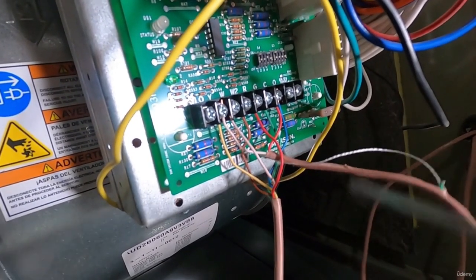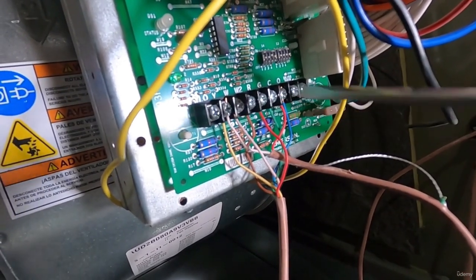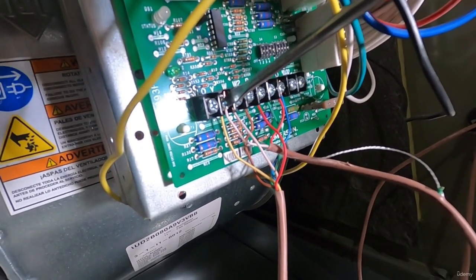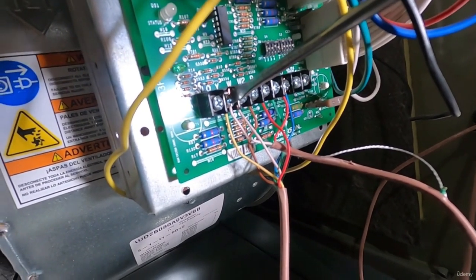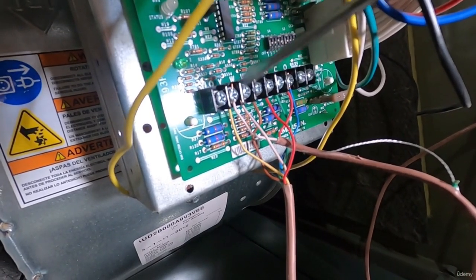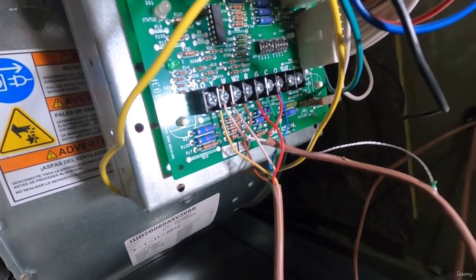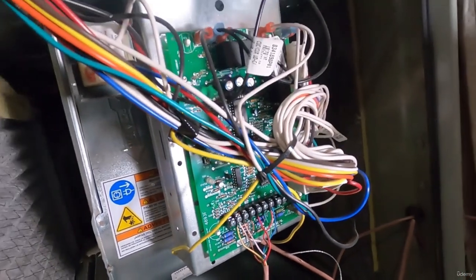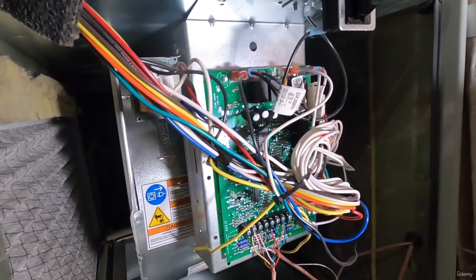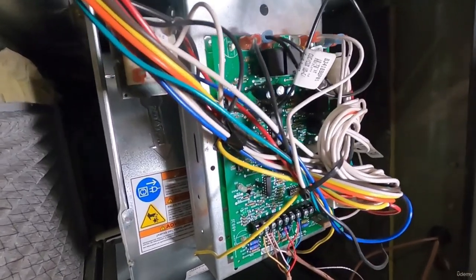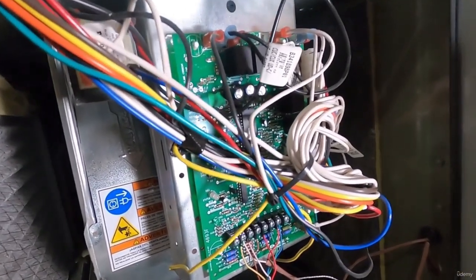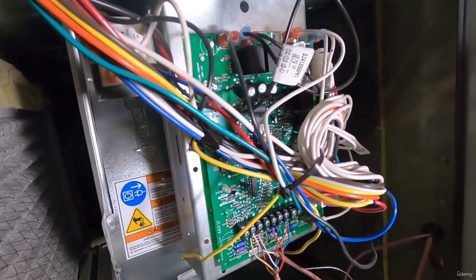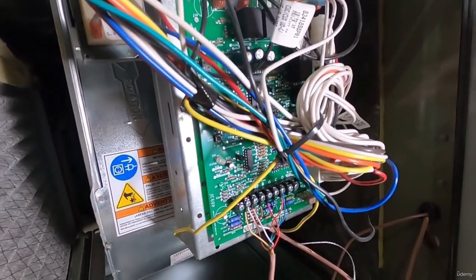So the condenser has 2 wires. One is on common and one is on Y. So as soon as you apply power from the thermostat, call for cooling, that voltage is going to come down here to Y and energize that condenser right off the bat. And basically in the cooling mode, this control board is just going to really just turn on the blower. Now there's a lot of other functions on here, but that's going to be for the furnace. So right now we're just mainly concerned with the blower motor, because that's really all that it's going to run